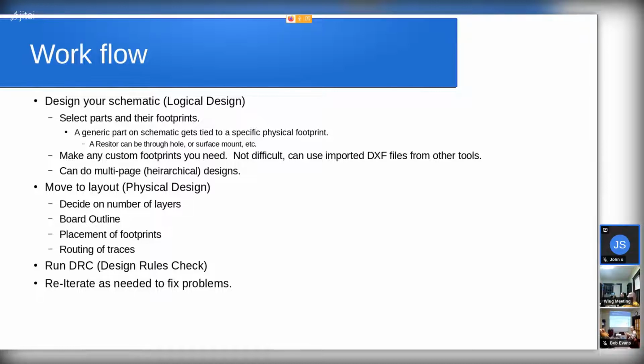routing signals in and out of that becomes really tight because there'll be 3 or 4, 5 or 10 rows in, and you want to get that signal out. You either have to go down a layer and then come out, and it gets really complicated to do that. I don't know anything. I'm talking like I really know what I'm talking about here, but this is a level of work that there are people who do full time because it's a real skill to be able to understand this, and I don't.